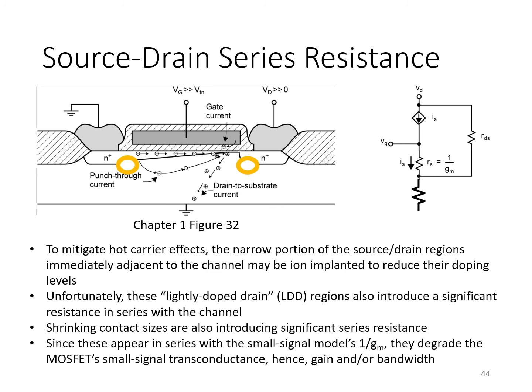The small signal VGS that's applied between here and here is now partly lost across the LDD resistance. And so that reduces the amount that shows up here across RS, and which then gets multiplied by GM and turned into small signal drain current.